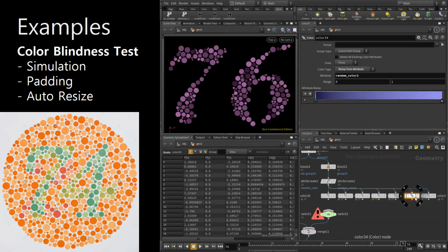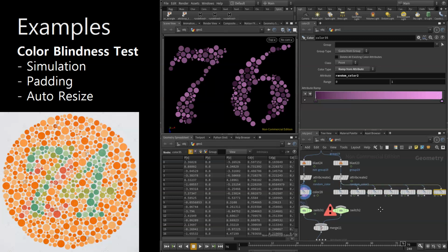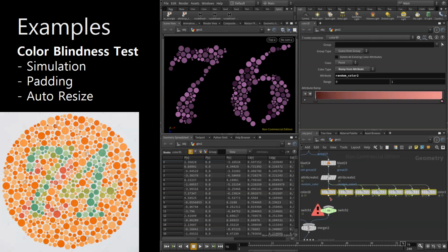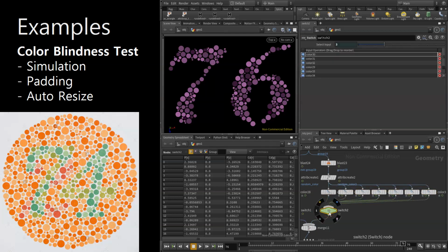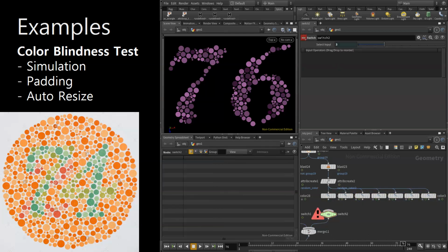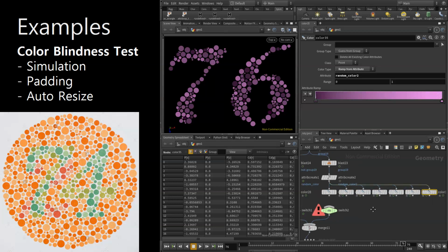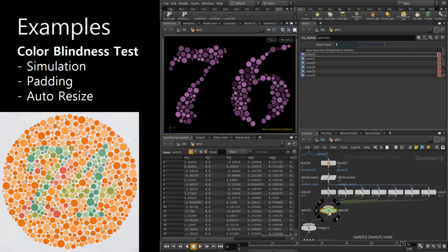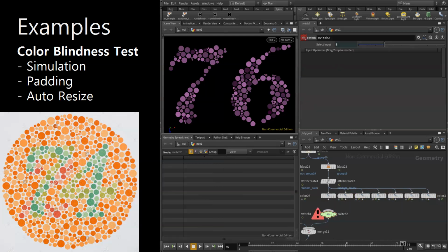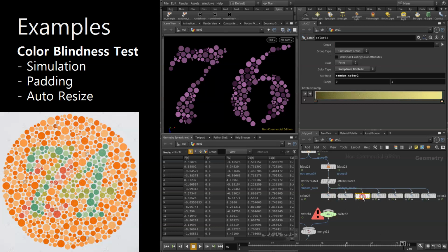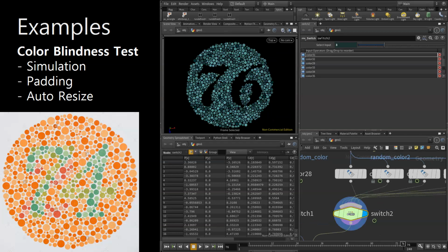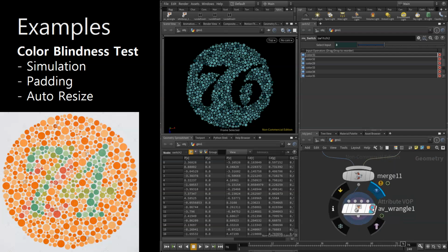Likewise, copy colors and switch subs to the background, then press Shift R on the switch node to send red to the back, starting with orange and ending with red. Then even if both switch nodes are equal to 0, the numbers are red on the number side and orange on the background side, so that the same color does not appear at the same time. You see, now we get different results per every frame.